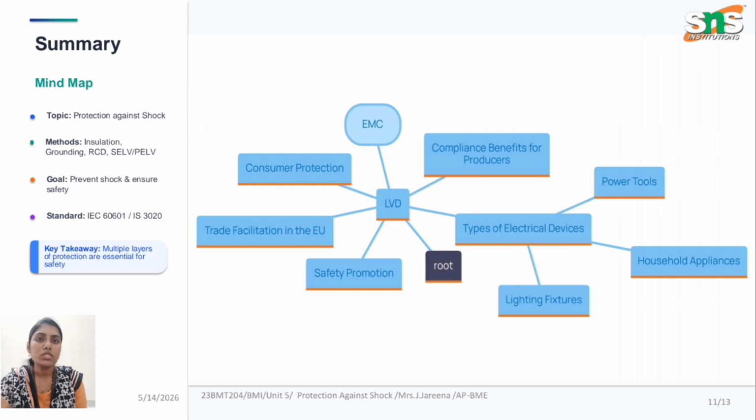Finally, in the summary of this topic, we have discussed the reason a person gets shock and the different hazards caused by shock. Most importantly, we have had a clear discussion of protection methods. We have covered four types: proper grounding and earthing, insulation and barriers, RCD, and finally low voltage and protected low voltage. So we have covered a few protection methods.